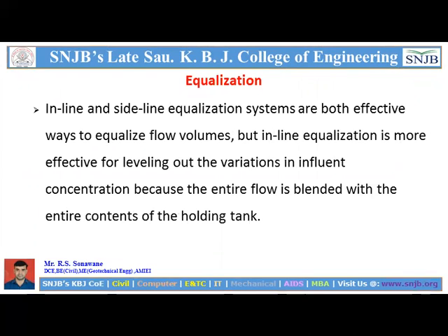So in equalization, there are different types of methods. For example, you can see here inline and sideline equalization systems are both effective ways to equalize flow volumes, which relate to the volume. But inline equalization is more effective for leveling out the variation in influent concentration because the entire flow is blended with the entire content of the holding tanks. So mostly inline and sideline, there are the two systems.